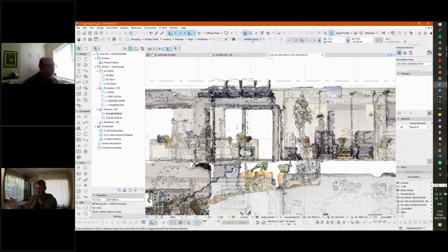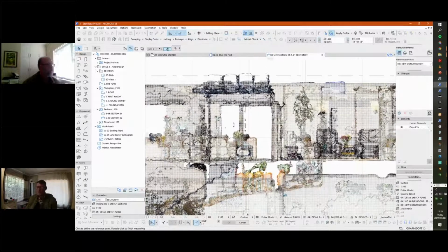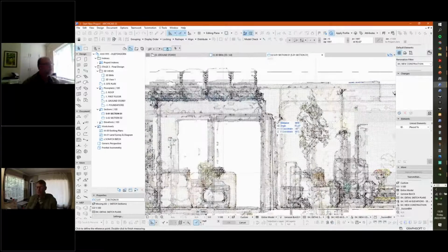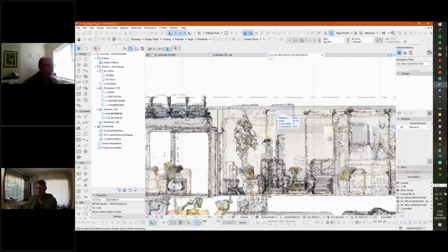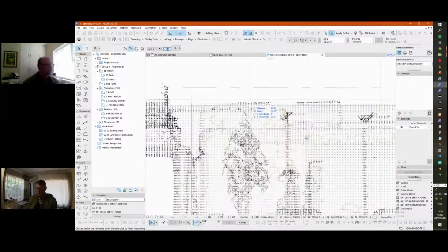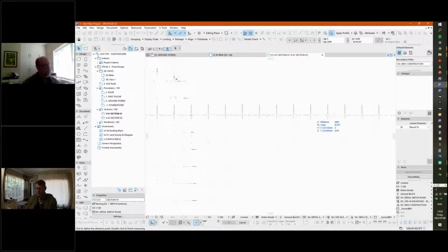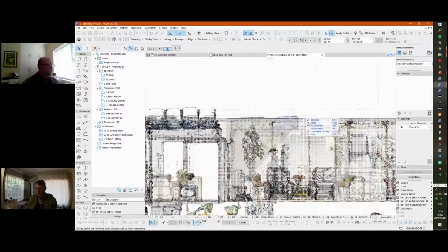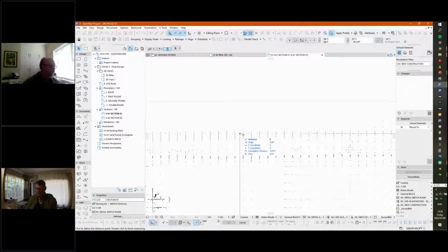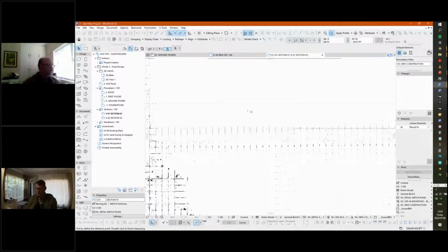I'm just going to also, while we're busy with this, measure to the ceiling. And if you look at these point clouds, you'll see indents going up, some of them going up, but there's a common line that starts to appear within the point clouds. And it's this line here. So you reference that point there for the height of the ceiling height.